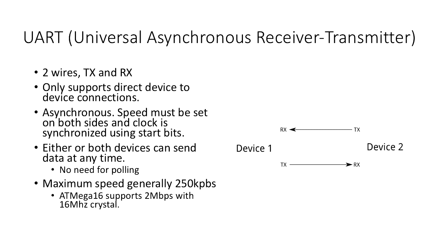When you have SPI, the advantage is it is synchronized. Without synchronization, how can you send the data from this side to this side? You know what I meant? When you send data, you are using a clock here. If you use a different clock here, you can't process it. So in SPI, there was no problem with synchronization because you are transmitting the clock.